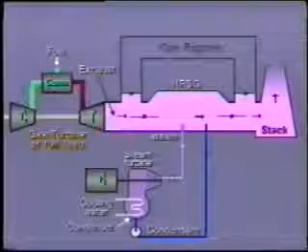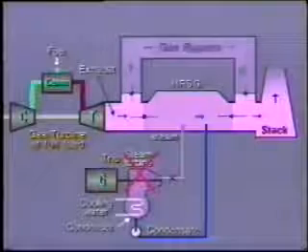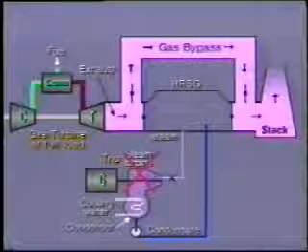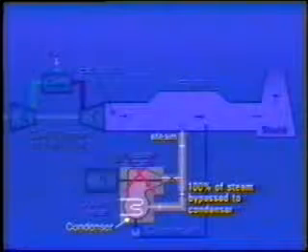We can already see here an advantage of the gas bypass around the HRSG. In the case of a steam turbine trip, the exhaust gas can be immediately directed to the stack, thus diverting flow from the HRSG. With no gas bypass, it would be necessary to trip the gas turbine unless 100% of the steam output can be bypassed to the condenser.